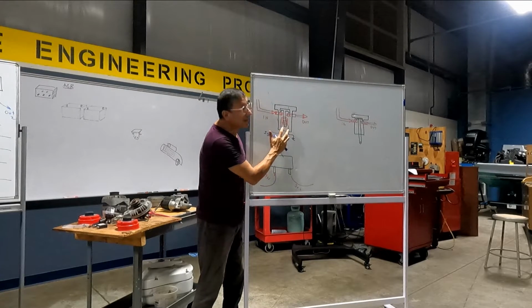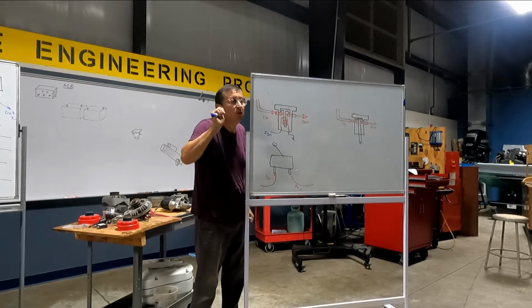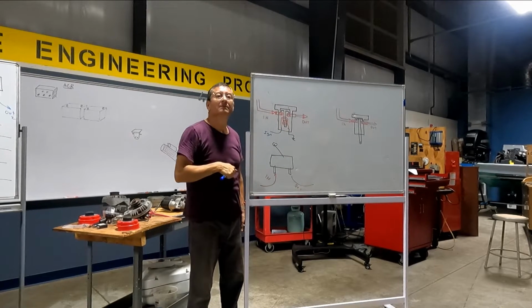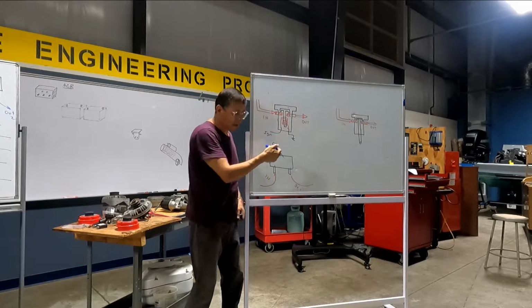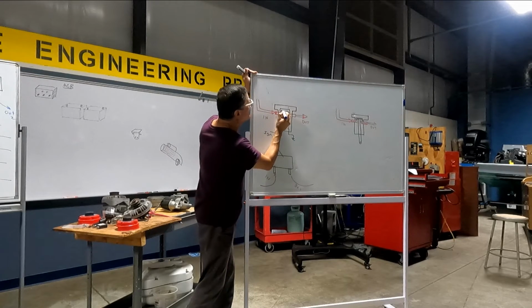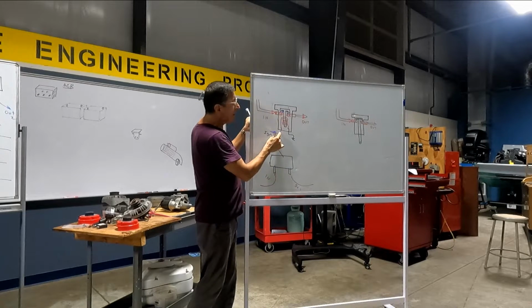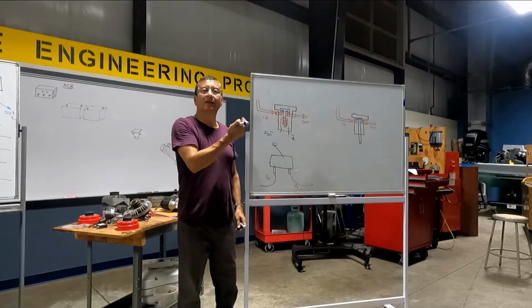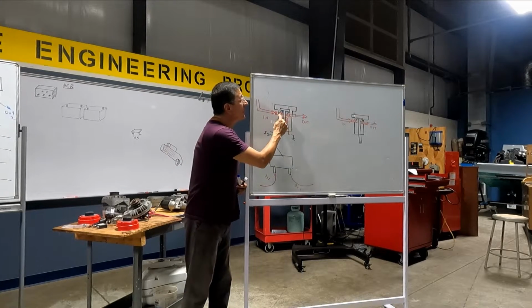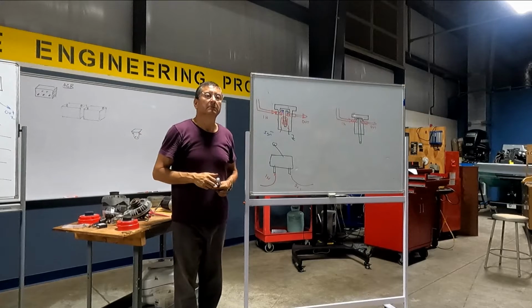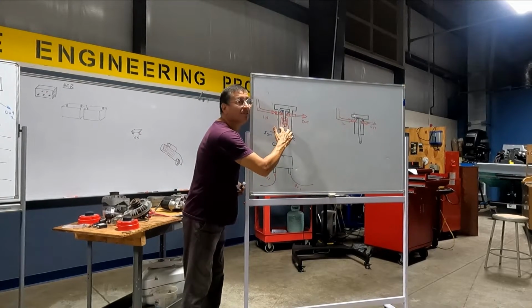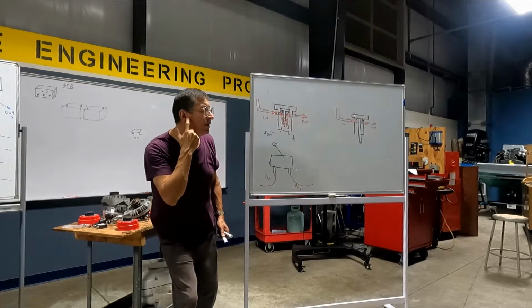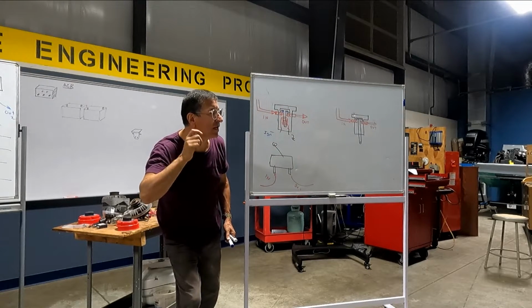Nice, no? It's a piece of iron, and I have a coil around the iron. When I bring the signal here from the ignition switch, what happens with the iron? What happens when I remove the power here? Here I have a couple of springs. What happens when I remove the current here? The springs open. And now this and this are not connected. What happens when I bring the signal again? The current passes through the other. For that reason, in the relay, you always hear click, click, click.